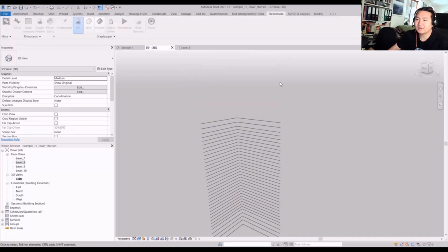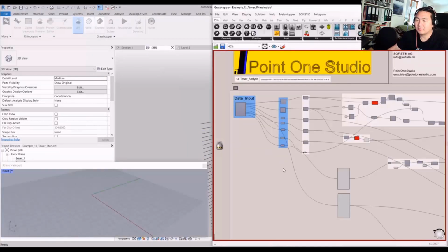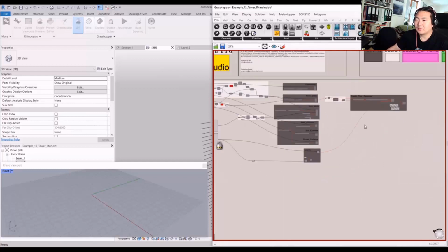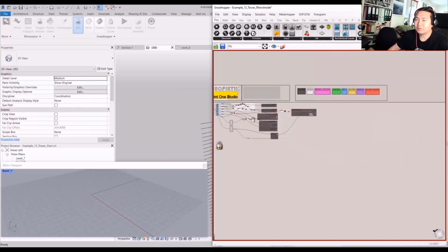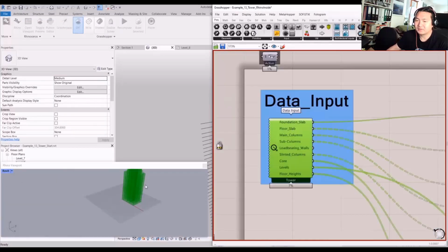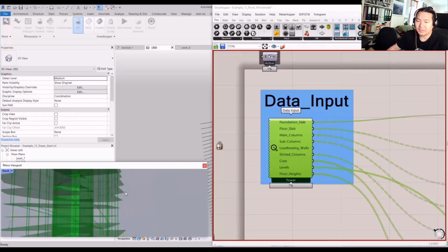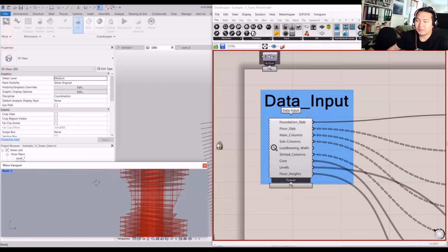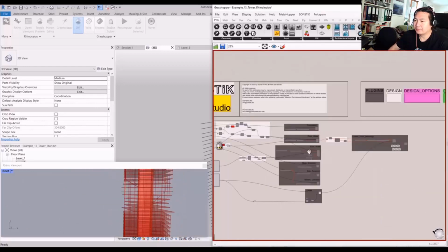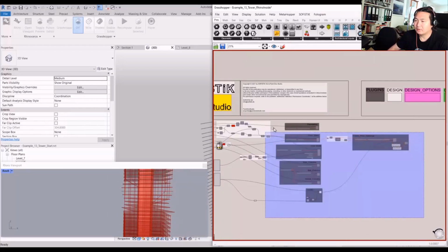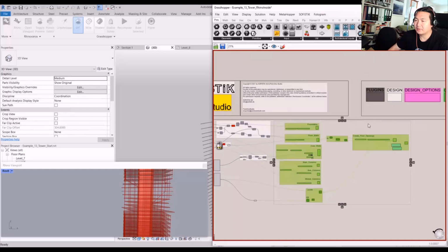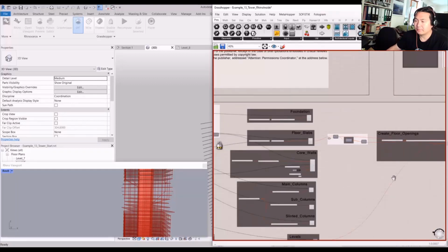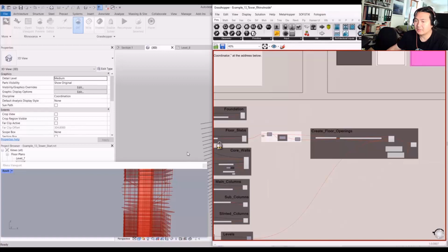So once the workflow is set, now let's imagine that the confirmed analysis model needs to be documented in the BIM platform. So we use Rhino.Inside.Revit, and let me compute to bring the updated geometry from the design script. So we have here in the Rhino.Inside script, now the design model is updated. And now I'm going to apply the entire geometry process. So just enable it, and I'm going to recompute all the elements in Revit at once.